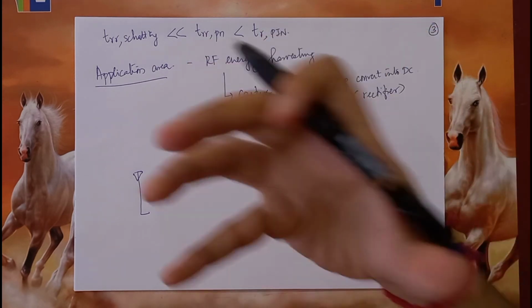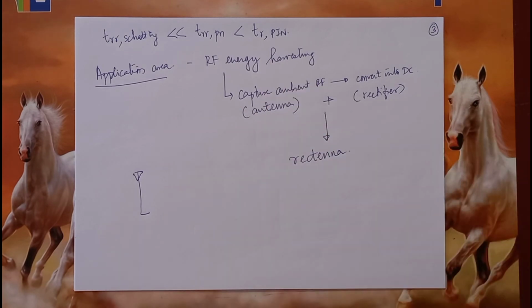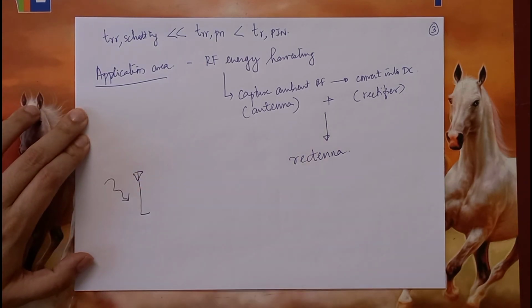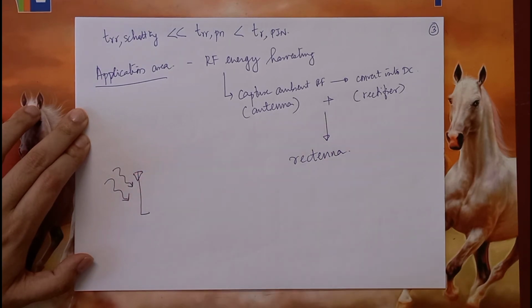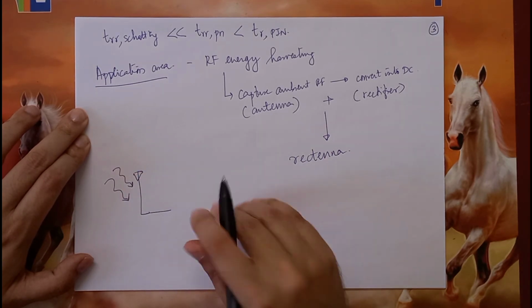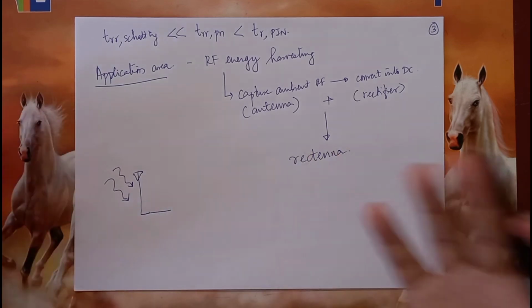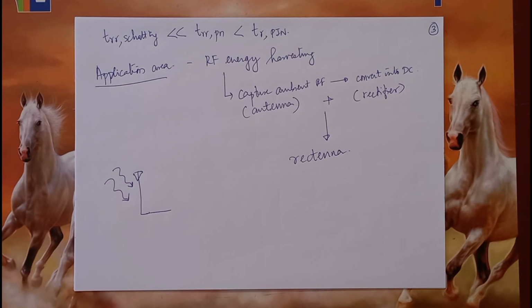That is the capacitor, because once you charge it and don't give it an easy path for discharging, it will be able to hold on to the magnitude peak of those rectified signals. So if I have an antenna that is able to receive RF signals, you will have to combine a rectifier with those capacitors, and therein we have a very nice circuit that is called a voltage doubler.